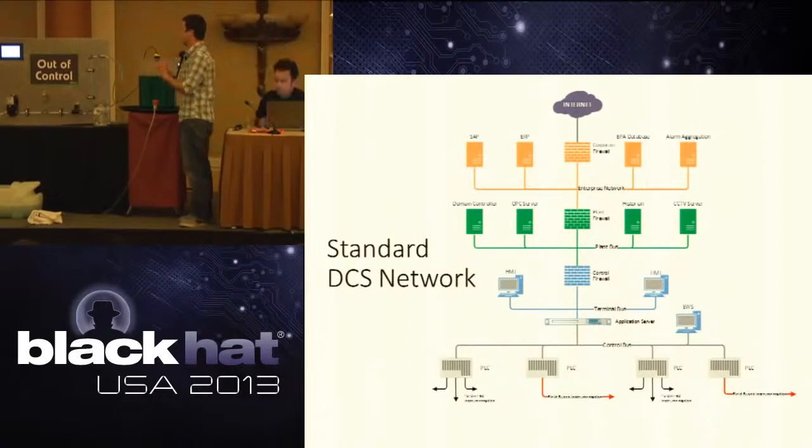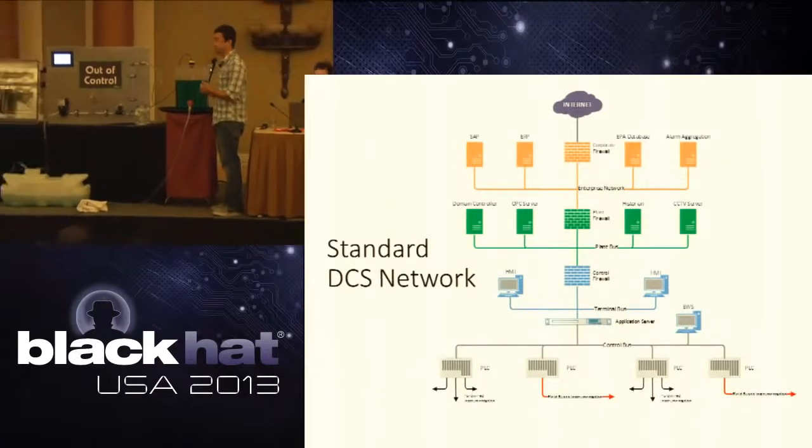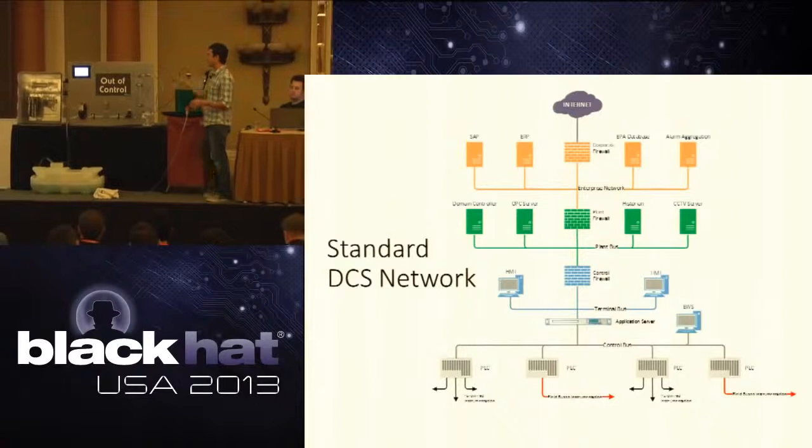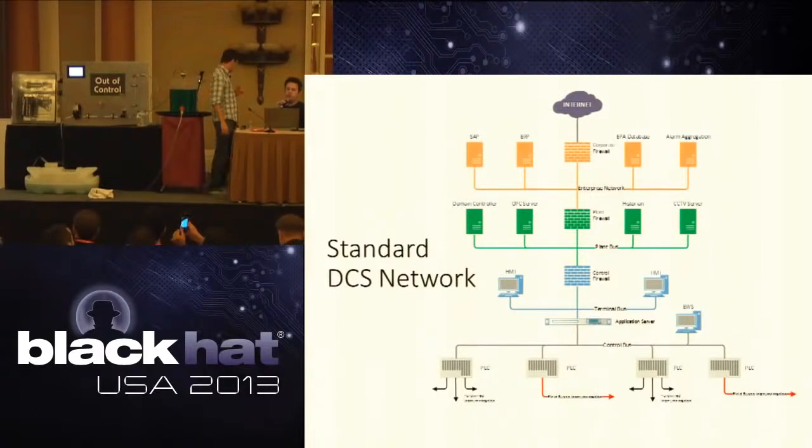When we talk about a DCS network, if you've never heard of DCS, it's a distributed control system. And usually we have that control bus, but that control bus needs to be very real time, and it's usually all part of a plant LAN, essentially. So DCS is usually used in factories or automation, all contained within one location. Exactly. It's when you require real-time data. SCADA is a little bit different.